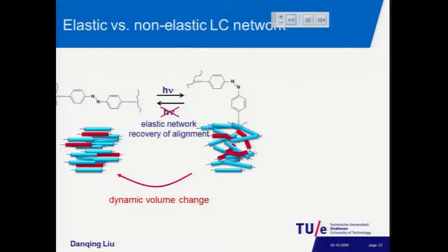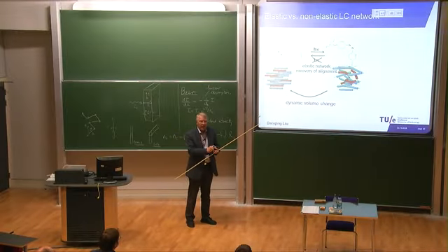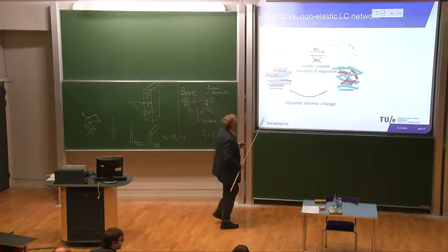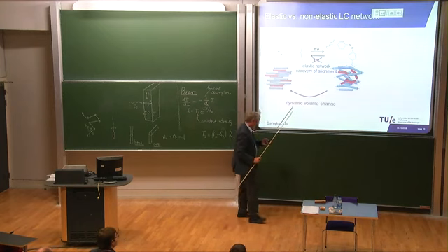So this is, again, somewhat simplified, the model that we still have. We have our liquid crystalline network system, straight azobenzene molecules. Then you start exposing, they bend, and you form free volume. And the free volume is the origin of the density decrease. As soon as you stop the light, it goes very nicely dynamically back. Actually, it goes very fast back, much faster than if you would record this isomerization reaction in the solution. There are stresses which are promoting basically this backward reaction.